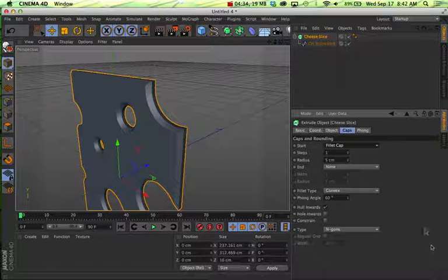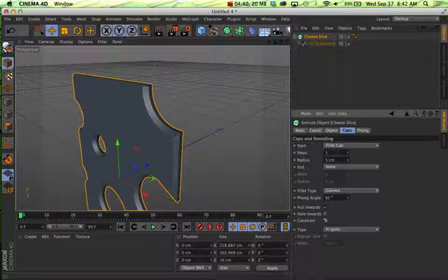Well, to prevent that from happening and to keep your spline true, you want to go ahead and hit Constrain down here, this checkbox. That'll keep our spline staying the same size. If you're bringing in type or something like that, if you're doing an extrude, you definitely want to make sure that's on. For this, it wouldn't really matter that much. What it's doing is basically expanding enough so that whatever your bevel setting or your fillet setting is, it will not cause any weird polygons.